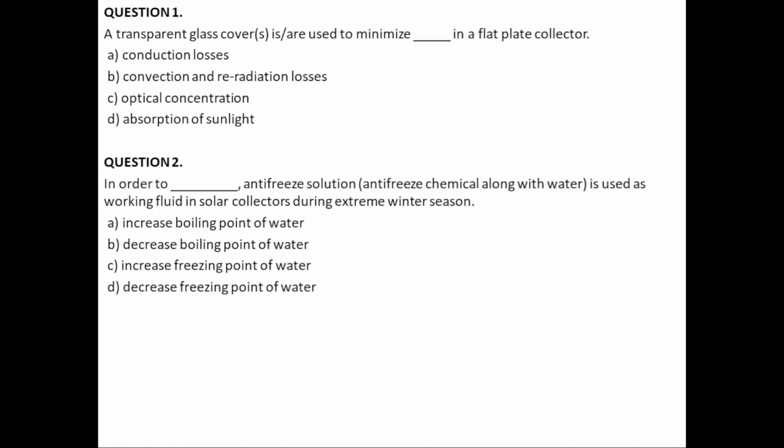That is an extreme condition which will be available only in certain locations in the world, but a minus 60 degree solution can be helpful to prevent this problem of freezing. The concentration is approximately 40% ethylene glycol with, I guess, the rest 60% water, but the exact concentration is available in the literature. You can Google papers on varying the concentration of ethylene glycol and its anti-freezing properties.